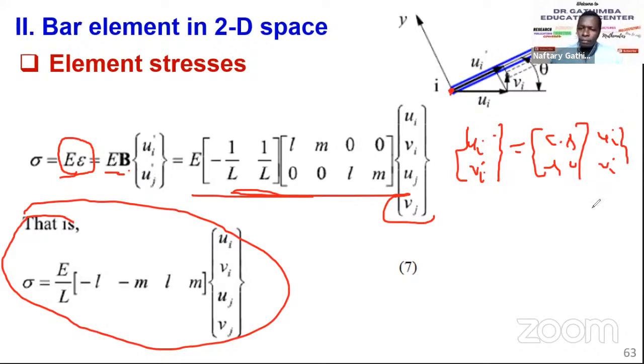For the stresses, the v is inconsequential, because for the stresses in the bar element we are talking of the strength over the area, the cross section. So we are concerned with the direction u for the individual member. So look at this again and refresh yourself with the strain displacement matrix, and then you are going to see how we obtain this part, and this part reduces to this part.